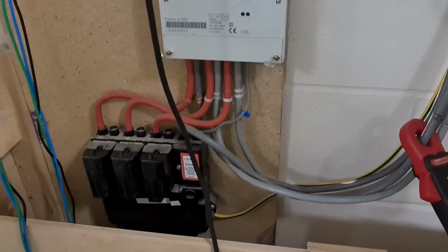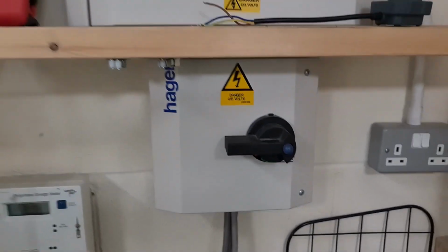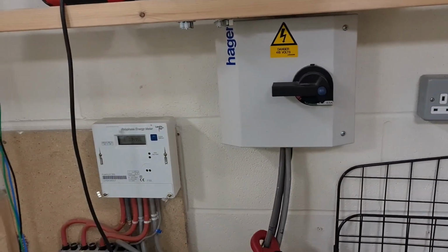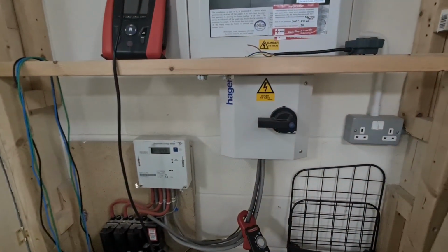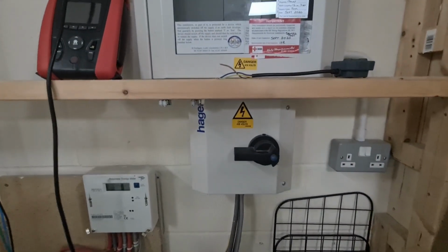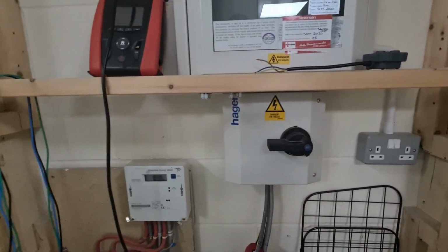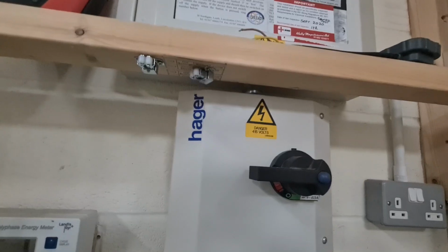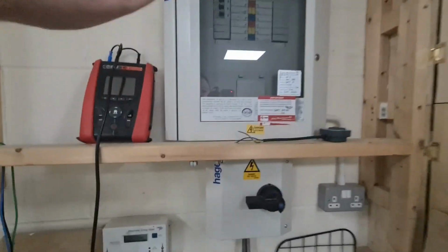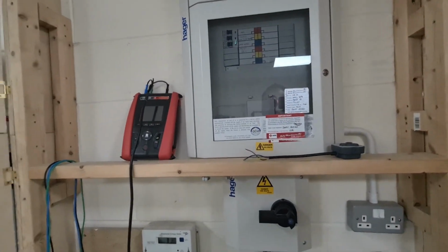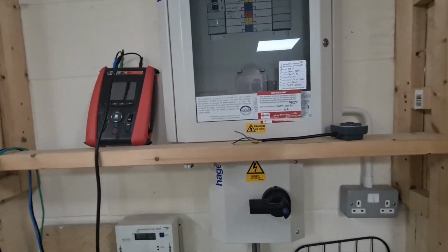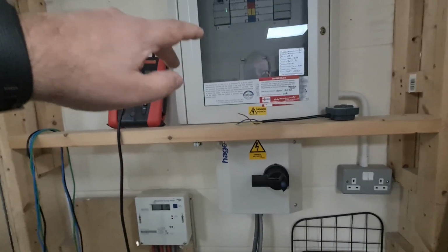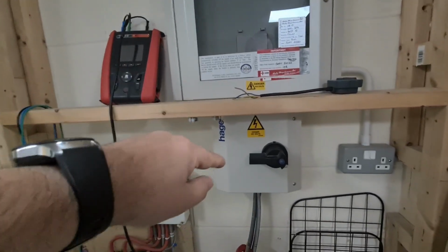You can see it's a TNCS head. We've got an isolator switch here. I've shown this on an earlier video before. It's a weird setup, and I think they did this to try and limit the earths of the rest of the building passing between each other. I don't know quite why they set it up like this, but there is a steel conduit between this isolator and this board, but there is a rubber grommet in there, if you like, that separates the two. So the main earth into here is only joined into this board through the earthing conductor within this.